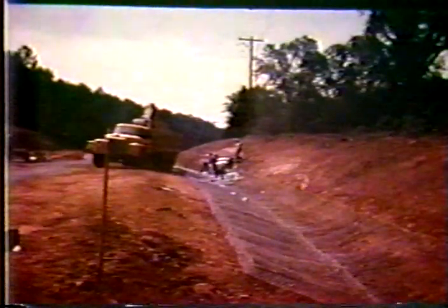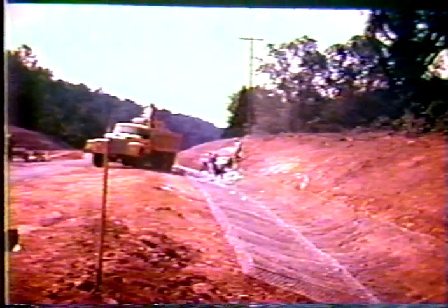You also can use gabions, the mattresses, for drainage ditches and controlling surface water runoff. Another good application is at bridge approaches where there's a river. It's not shown here to the right, but they're protecting the toe of the slope with a gabion wall. Those gabions there are probably about 3 feet in height, so that's about a 9-foot wall there. Also, you can use the same concept to protect the slope of a highway fill here, a small fill, perhaps less than 20 feet, but it's doing a good job.